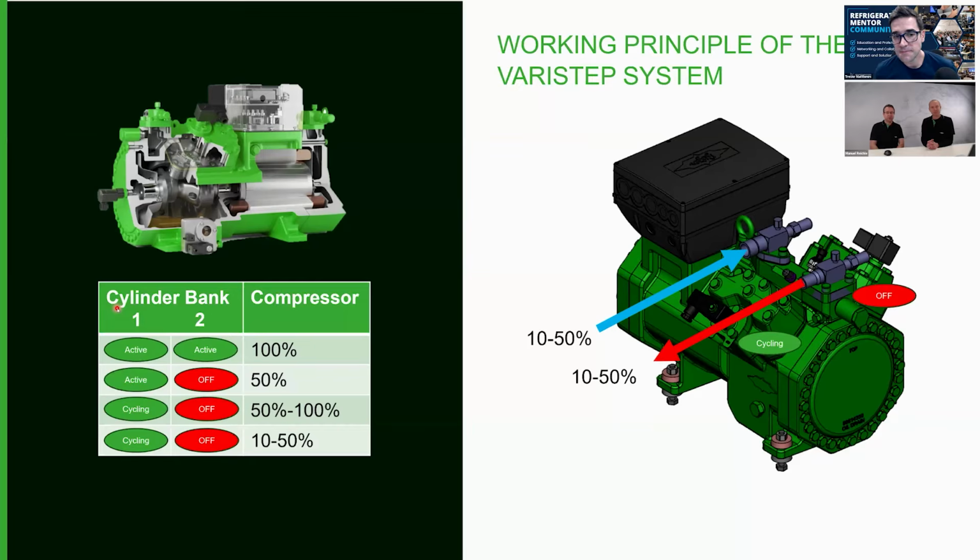We cannot simply stop the compressor, because the sensor cannot measure it, because the cycling rate doesn't allow it. We had to implement an intelligent function to have a cross reading of what is the real temperature now versus the measured temperature, and for how long we can accept the high temperature.